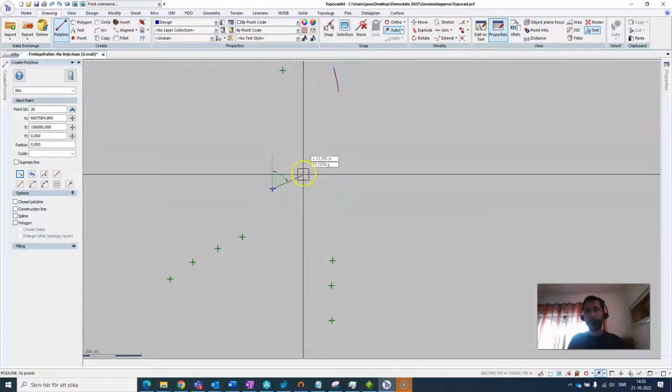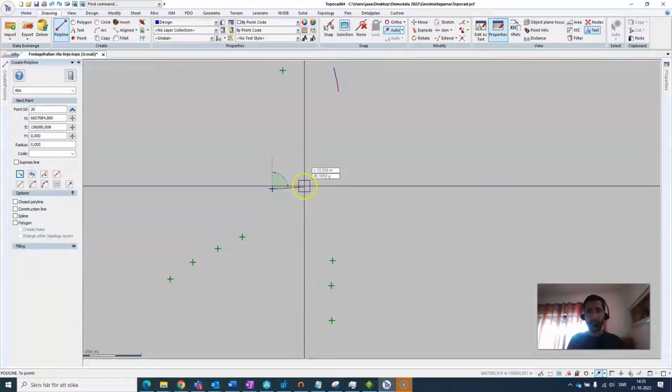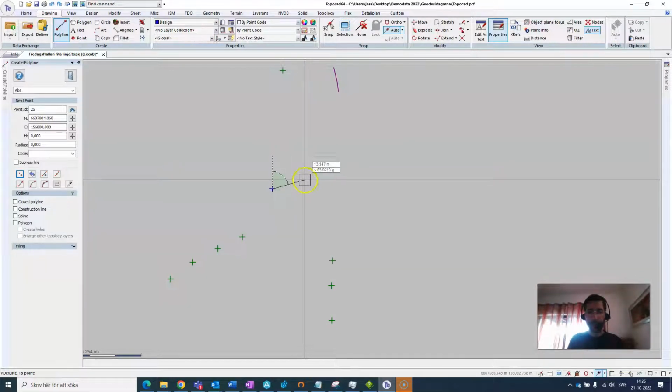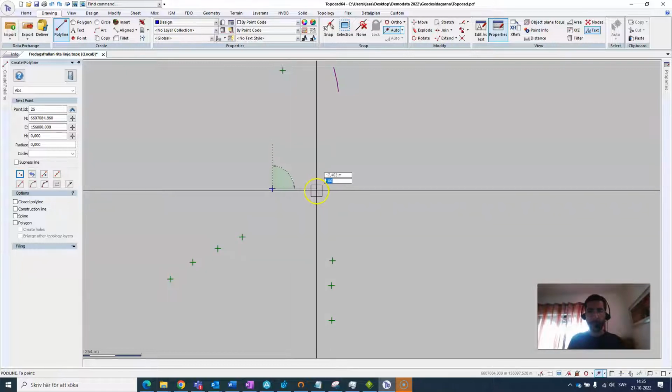So to use these windows, we just press on the tab key. So here you can see a little arrow on the length input, and if I press tab, now I'm on the angle. So let's input 100 gon, and now we see it.